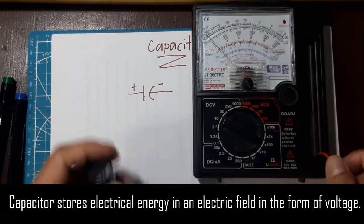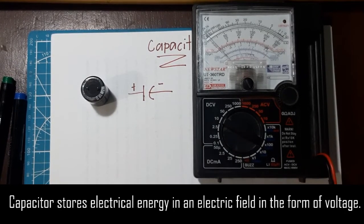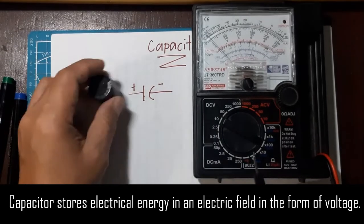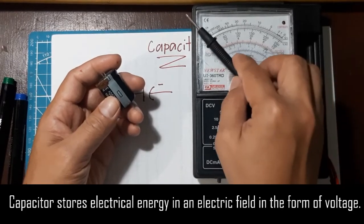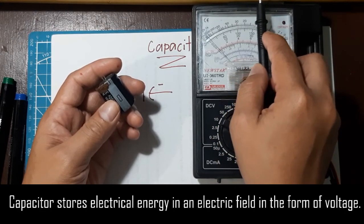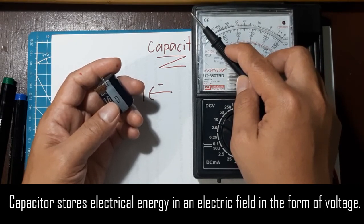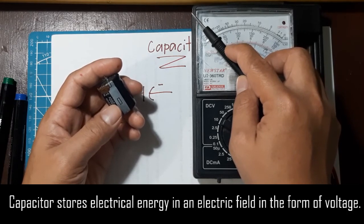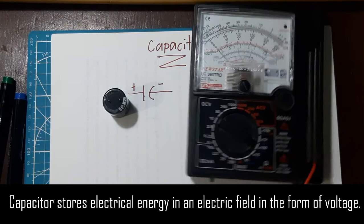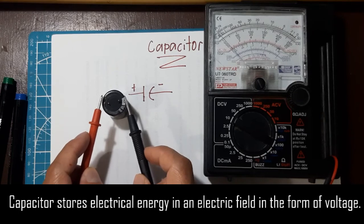To identify if our capacitor is working, we can use again our multimeter. So we just set our multimeter to resistance scale or reading, and then normally our capacitor, if it's working, will give us low resistance, and eventually it will return to the infinite resistance value. So what does it mean? Once we connect our test leads to each terminal of our capacitor, it will store energy.